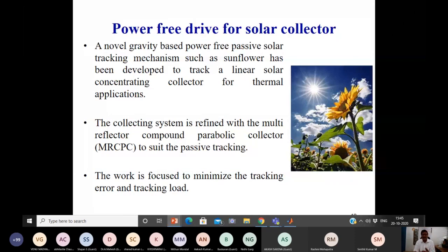We are able to drive means that becomes the perpetual motion machine. In thermodynamics, perpetual motion machines are defined. Perpetual motion machine means without supplying energy you are creating the energy. That violates the laws of thermodynamics. If it is violating the first law of thermodynamics, we call it perpetual motion machine PMM1. If it is violating the second law, that's PMM2.